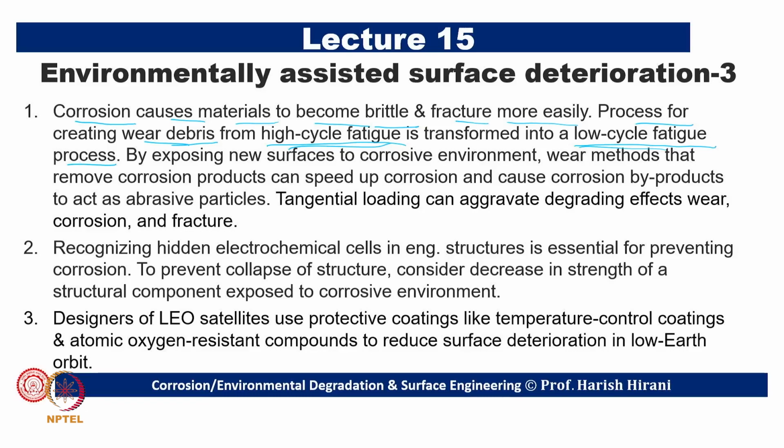Now, when corrosion happens, it really allows easy removal from a surface. When the new surface gets exposed, it is much more chemically active and further corrosion will occur. So, wear and fracture get associated with corrosion, and all three working together can cause a fatal failure or damage to the surface.